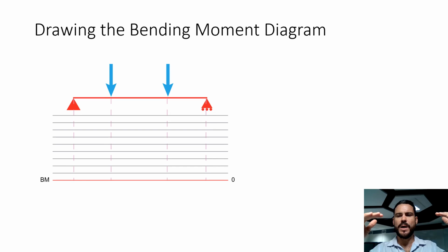We're going to draw in our scale. All the numbers that we ended up with were positive numbers, which indicates that we're moving above our line. Okay, that's correct, even though you can probably imagine that the bending force is going to be pushing the beam down. For whatever reason, even though the bending force is pushing the beam down like this, the bending moment diagram is actually going to be inverted, and it's going to look like a mountaintop. So don't get confused with that one either.